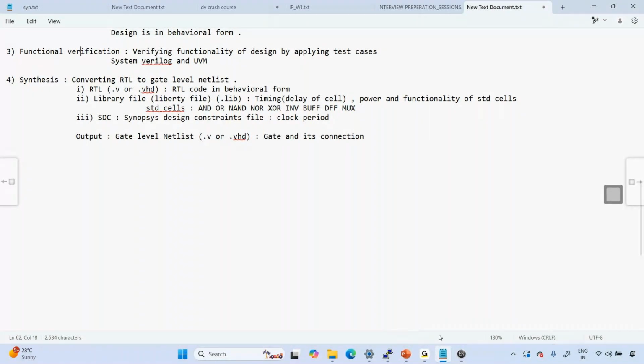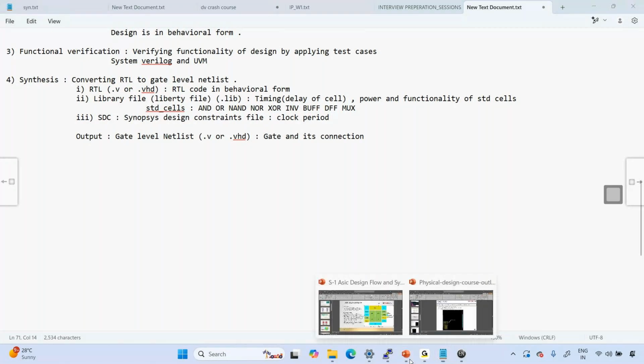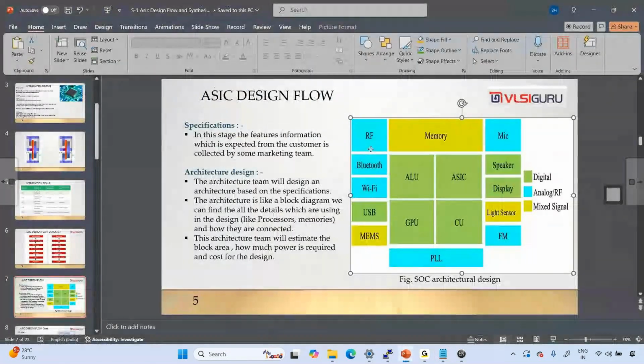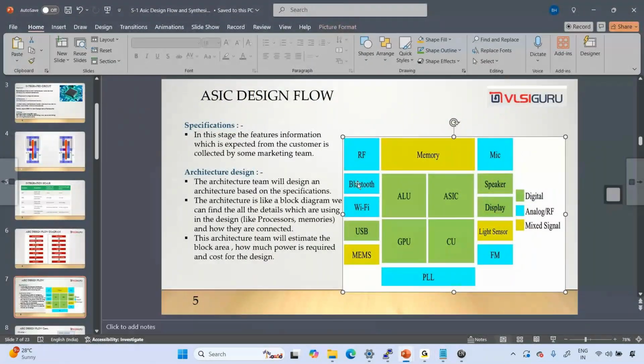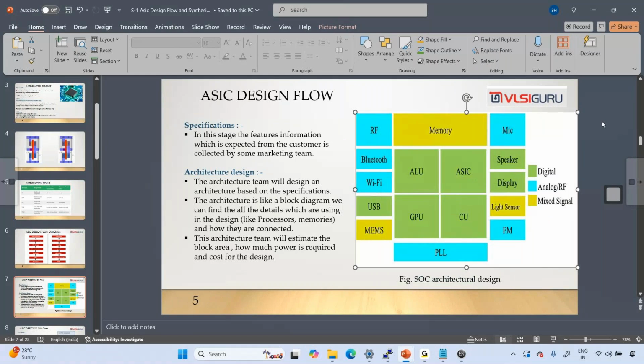Now what I am discussing here is what a gate level netlist is. For each block, I'll get a gate level netlist and they are integrated. In your UG classes, you may have written a parallel adder using a 4 is to 1 mux, and connected to make an 8 is to 1 mux.